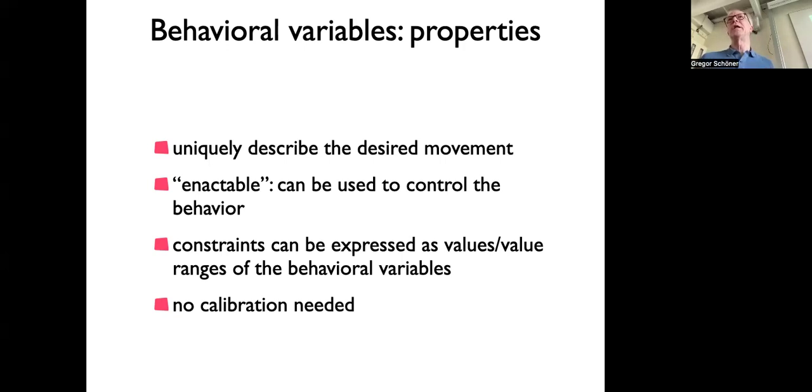So for instance, for the heading direction in the world, what you really would want to do is follow that time course that you generated for the heading direction. And to do that, in these kinds of vehicles, you would have to send some signals to your motors. And these signals would be essentially sensitive to changes of heading, right? If you want to go straight, keep your heading constant, all you need to do is send the same signal to the two motors, and you go straight.